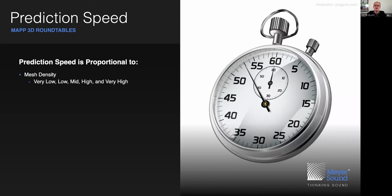That being said, you have 5 resolutions to choose from, ranging from very low to very high, and this is how you can manage speed versus accuracy. I can work at low resolution to get a first impression of, am I aiming the loudspeaker in the right direction? And then if I want to see the interaction between adjacent loudspeakers or arrays, I want more granularity, I can ramp up the mesh density to match my workflow.